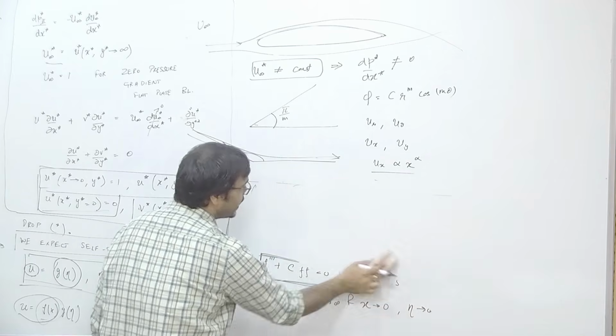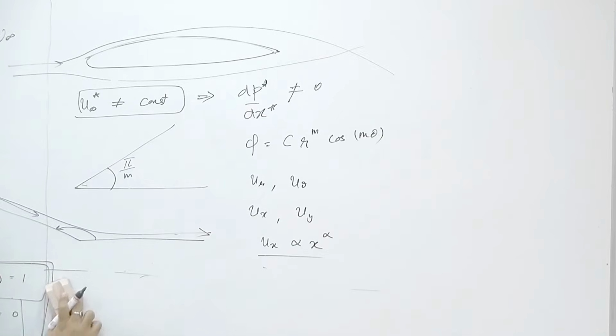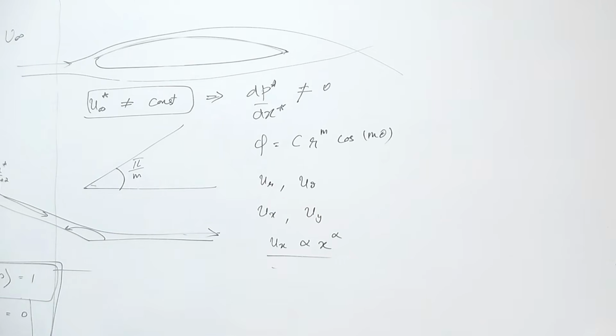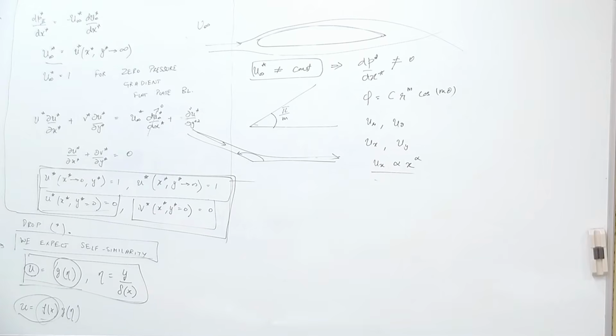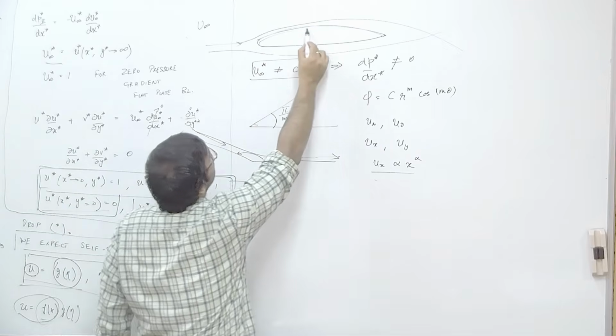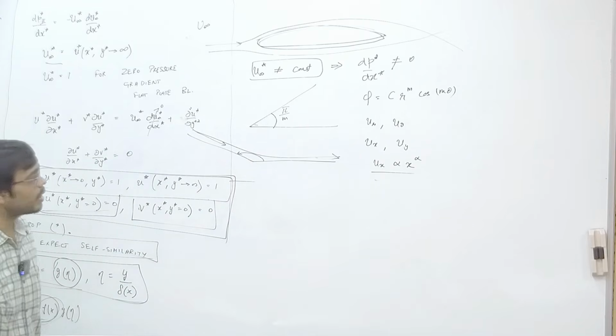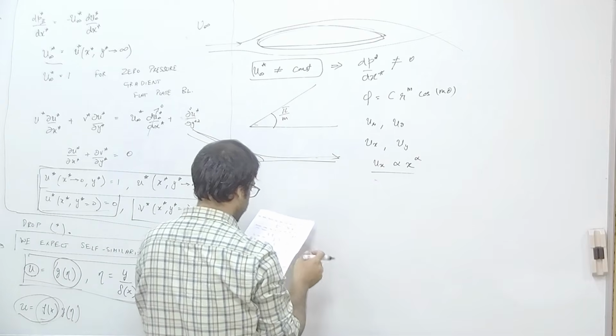That is exactly where the shortcomings of inviscid theory come, and that is where we transition, historically, from aerodynamic development based on inviscid theory to aerodynamic development informed by both inviscid theory and boundary layer theory. Because what we discussed just now, and what we are going to see in a moment, cannot be captured by our inviscid theory, and it is indeed important when you look at flow path shapes which induce a variation in velocity. Let us look at what happens when you have a pressure gradient like this.